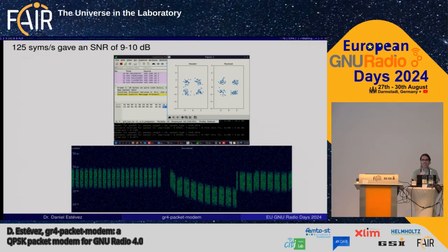And then the interesting thing is this is 5.9 gigahertz with this USRP, no GPSDO, no nothing. So the frequency oscillates like crazy, and I needed to tweak all the Costas loop parameters, but it worked great. I was like testing at night and, you know, change, recompile, run, and it ran. I will put up the SigMF file of this probably this afternoon for all of you to play with. And that's all I had.